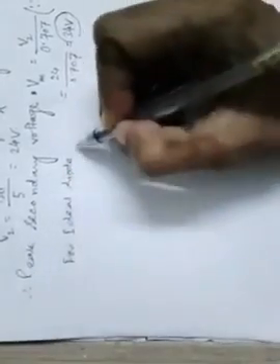Now if this diode is an ideal one, it will conduct right from 0 volt during forward bias, and there is no question of knee voltage or the cut-in voltage of 0.7 volt that is required. So in this case, for an ideal diode, the peak load voltage is given by this 34 volt. Vp out, the peak output voltage, is 34 volt. It is already found.